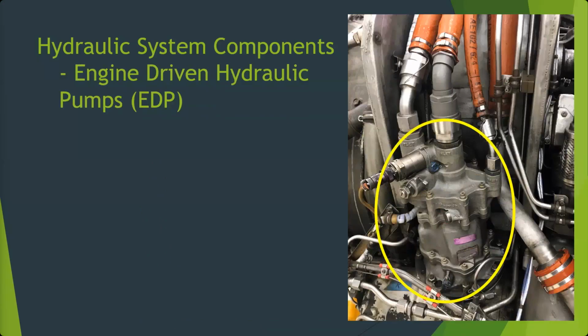Now this is an older pump. If you look down on the flange here, you can see there are studs with nuts holding it on. Okay. This is a newer pump that uses a V-band clamp, typically. So most of your modern stuff has gone away from studs and nuts like that and gone to a V-band clamp. It's easier to get a good seal, because you're putting it on, it's creating that tension all the way around. It creates a nice even holding power. Whereas something like that, the flange can warp and stuff like that.